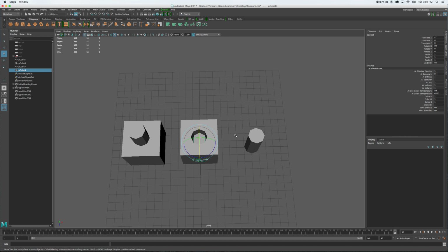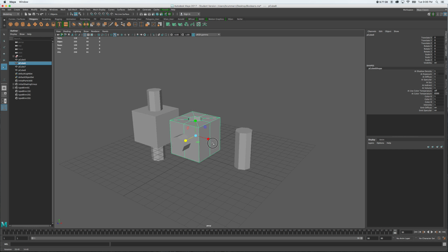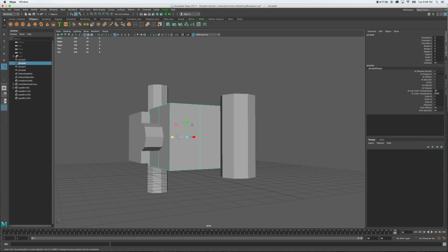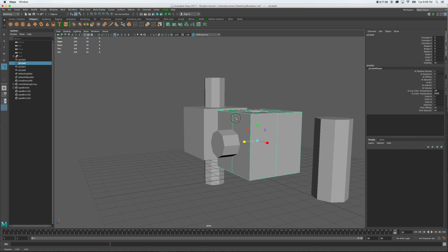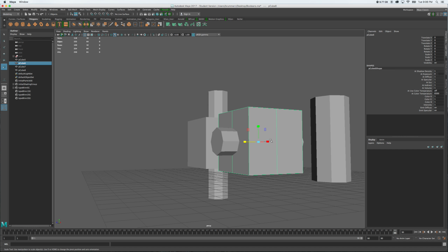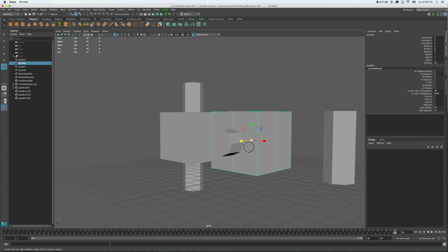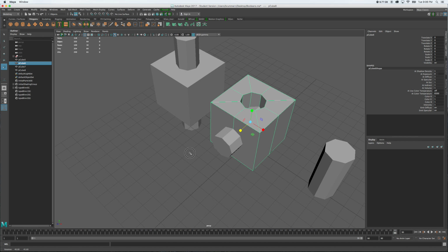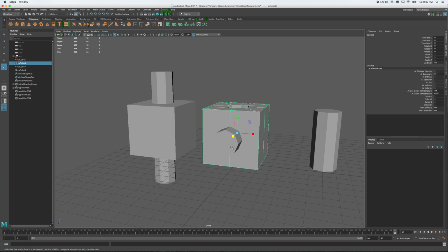Now we can generally already tell that if I'm going to cut a hole through the center of this guy, based on the current geometry, I have no center line. So I have a center line vertically. Yes, technically moving in the horizontal, but there's no vertical center line here, right? So there's no horizon. What I need is a center line here so that I don't have to do more work combining vertices together. If I cut this hole now, I'll go ahead and show you.